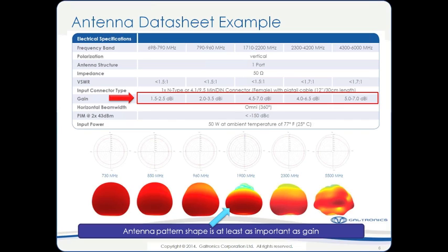Yeah, so we made the comment earlier that our antenna patterns are directed towards below the ceiling, and we're actually relying on that bounce off of the concrete floor or whatever structure is below. The presence of multipath is required to be able to separate those two transmitted signals in a 2x2 MIMO system. So you can imagine, without multipath, I'm not able to achieve my 54 megabits per second or whatever 100 megabits per second that are available.